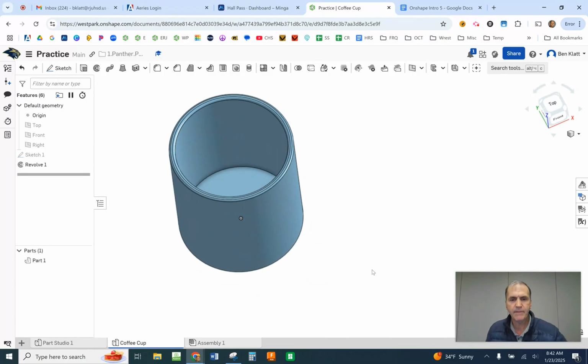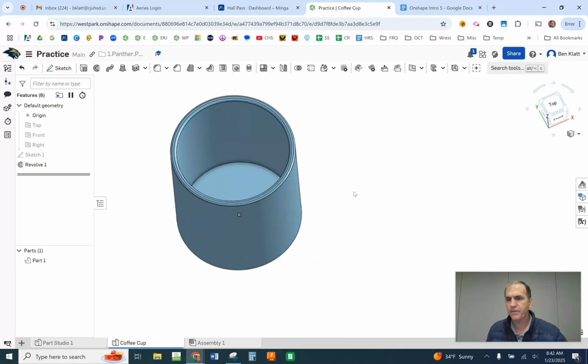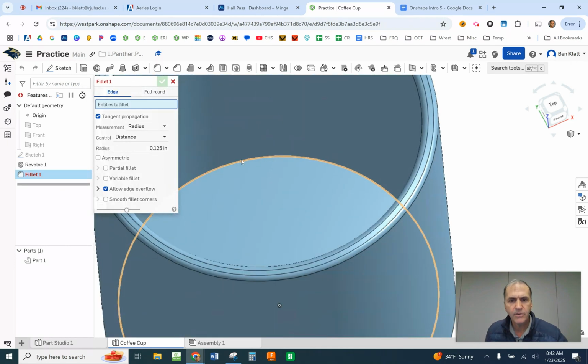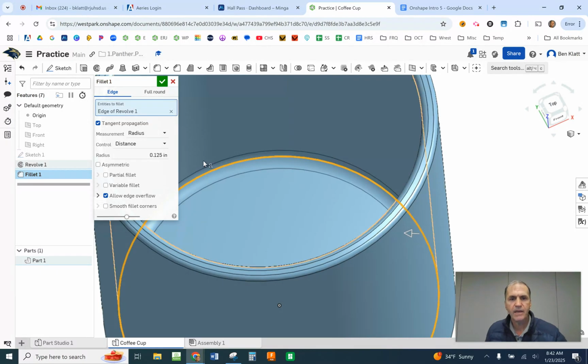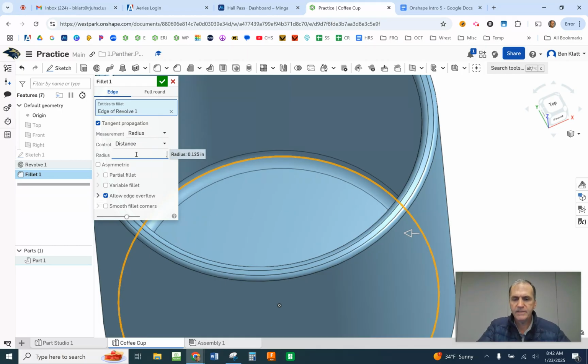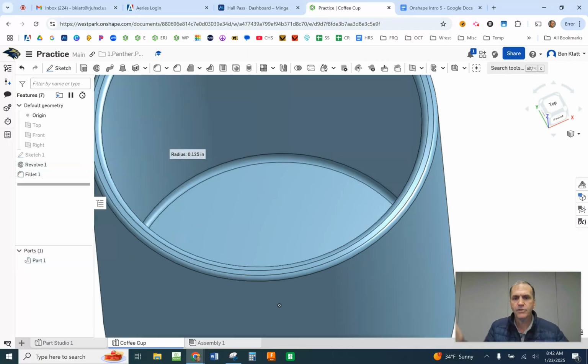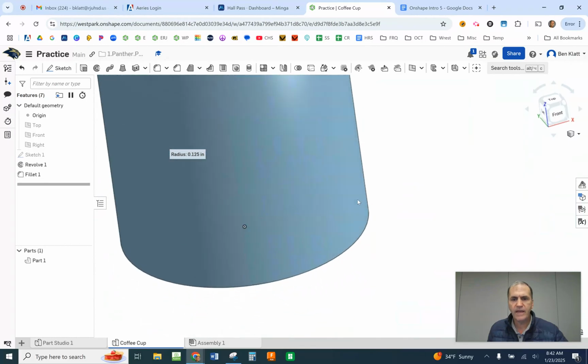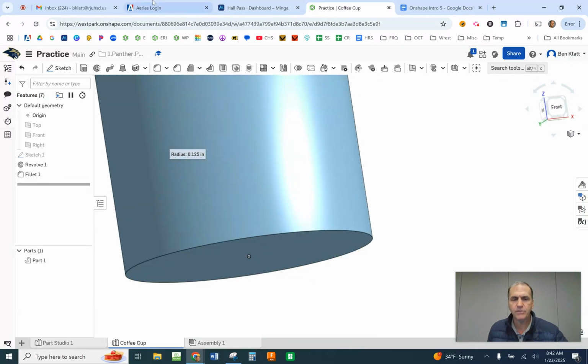I'm going to do those same two dimensions. This time we're going to do a solid fillet. So click that. We're going to click that little inside edge down here inside. Click. Okay. Now it's automatically choosing a radius of whatever the default is. Yours might be different than that. We're going to make that 0.06 like we did on the top. Enter. Enter again. We'll put it there. Okay, we've rounded it over, and now we're going to round over that outside edge to 0.04.